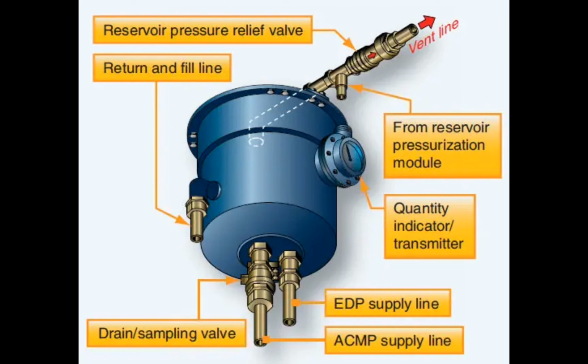What is the purpose of a pressure relief valve in a hydraulic system? Limits system pressure. What is the purpose of an unloading valve in a closed hydraulic system? Allows fluid from pump back to the reservoir. Pressure regulator. Low pressure fluid path from the pump back to the reservoir when system has no flow requirements.